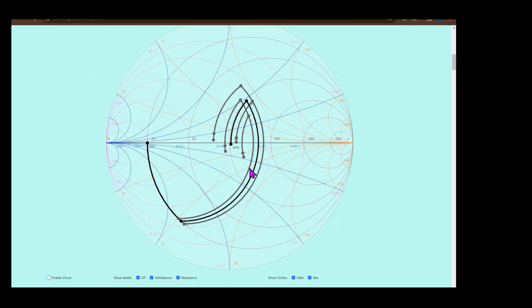There is no such thing as getting a perfect impedance match every single time. Every circuit that you build is probably going to have plus or minus 5%. Maybe on an integrated circuit, you might get a little bit better than that if you make a big enough component, but it's probably also going to be pretty close to 5%. So normally when I make a spec for a circuit, the spec will say that the return loss has to be better than, nobody ever says minus 10 dB because you want it to work over PVT variation, so they'll say minus 15 or something like that. If you have a really mean manager, they'll tell you minus 20.